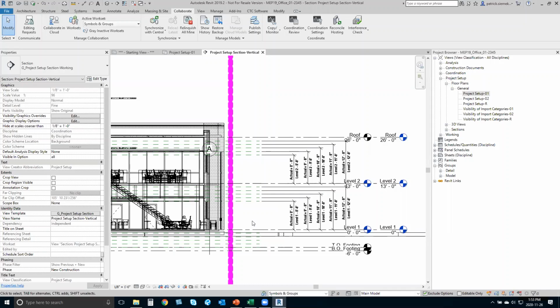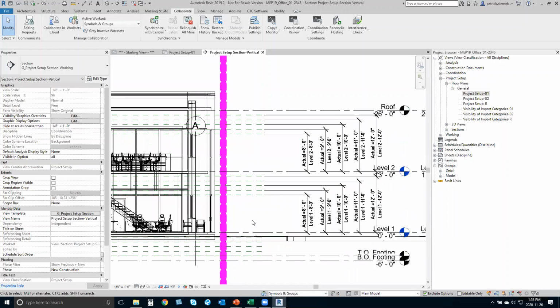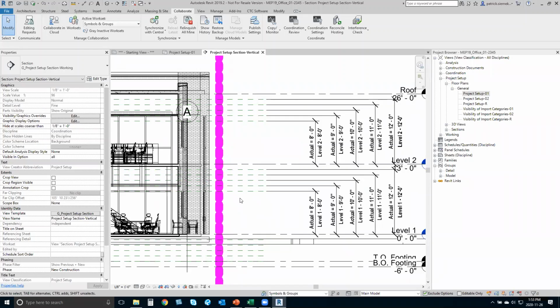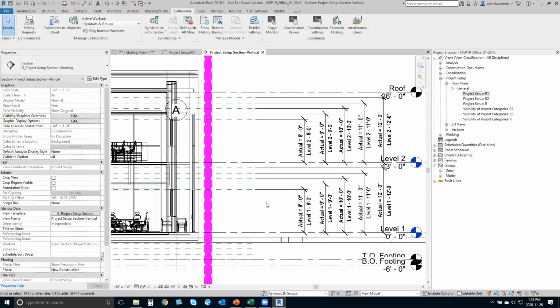So in a case like that, there are already going to be reference planes, which then you could host your elements to those references. Also, even if there are architectural ceilings inside the place, but you want to have the control of when you do move up and down any element associated to that ceiling, these reference planes are here for you to use. You could add them, you could also remove them, but initially you're going to have those reference planes ready for you to use inside of the project.